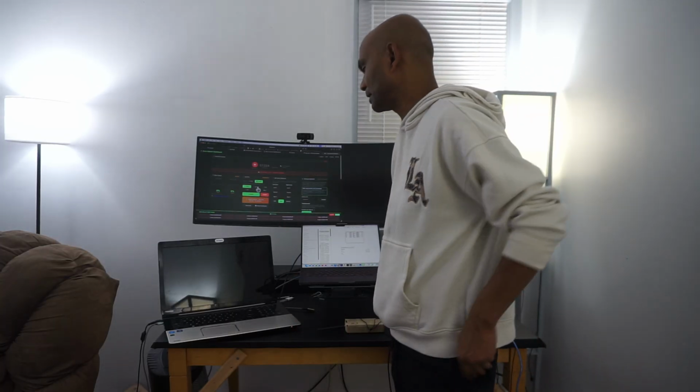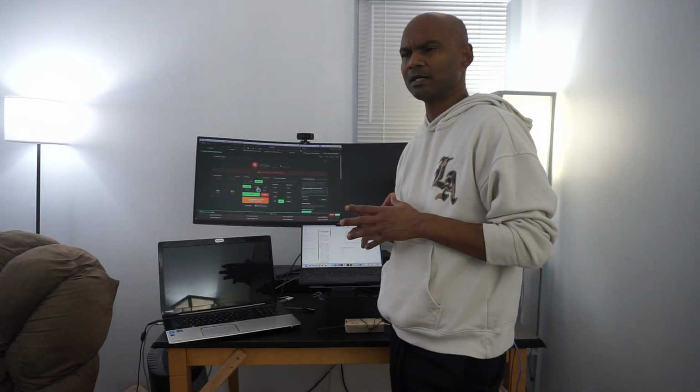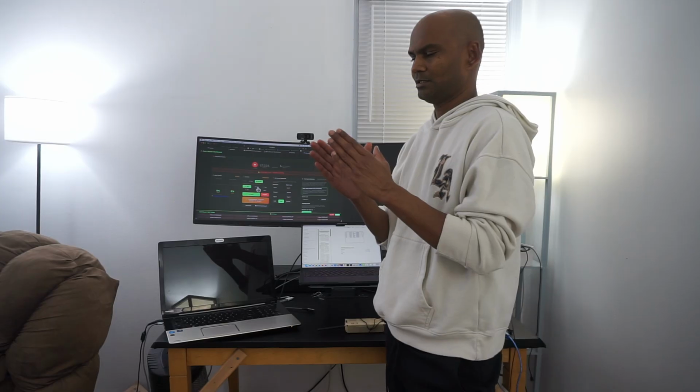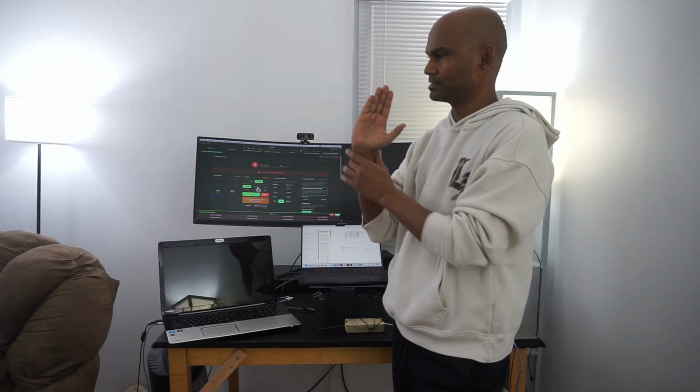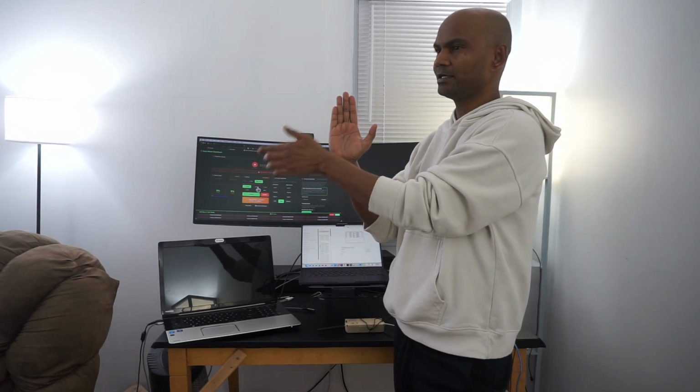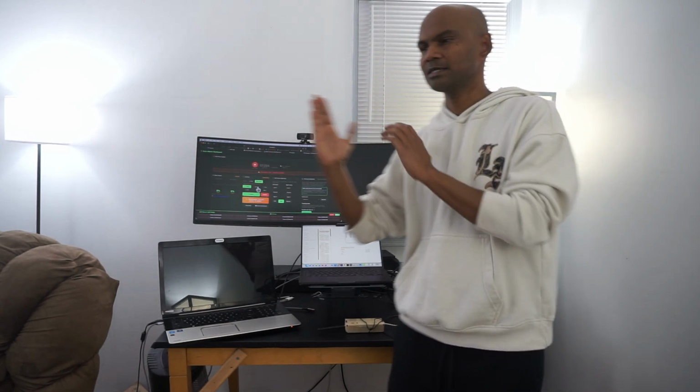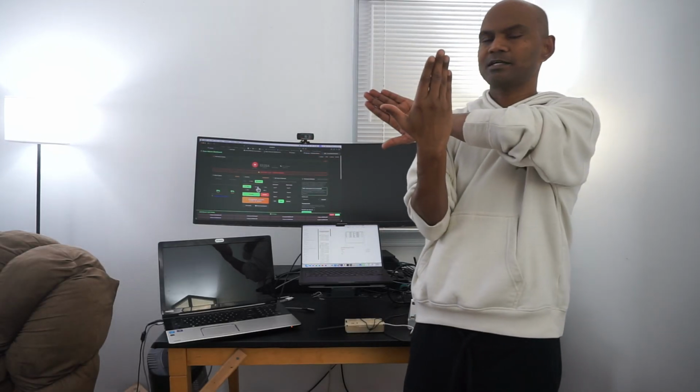The biggest problem I'm running into is calibration. The voltage expected by the mower is off because there is one Hall effect sensor that is connected this way, high and low, but they have taken the same connector and connected it on the other side because they could not find 2 different types of sensors.